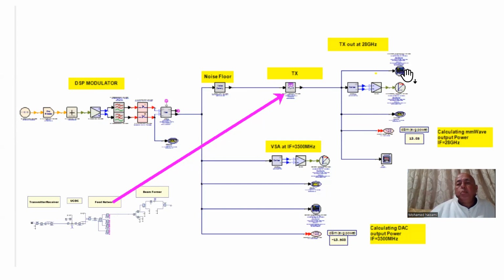Then I grab the output and take it into a demodulator first that demodulates and calculates the EVM. And then I take it into another signal analyzer, which displays real, imaginary, the constellation, a whole variety of stuff. And I have a spectrum analyzer in here to monitor it and look at the spectrum. And then I have a sink in here that takes the signal in and computes the power.